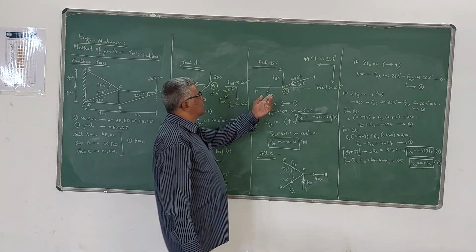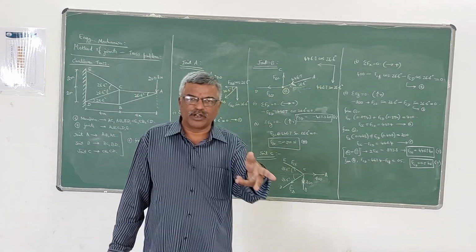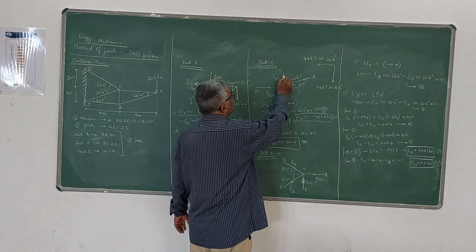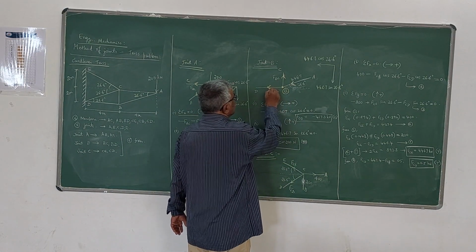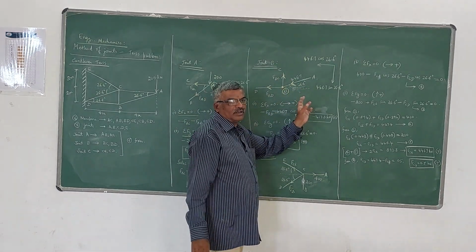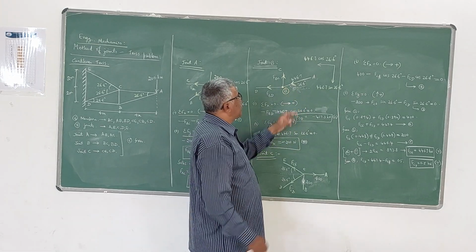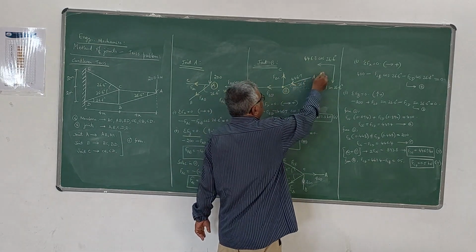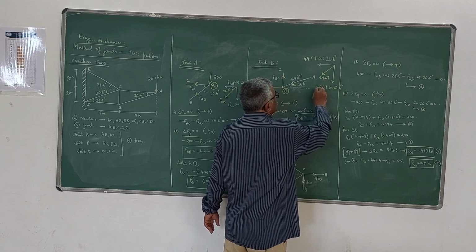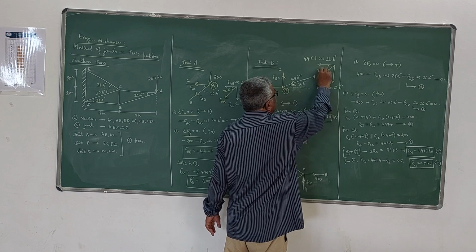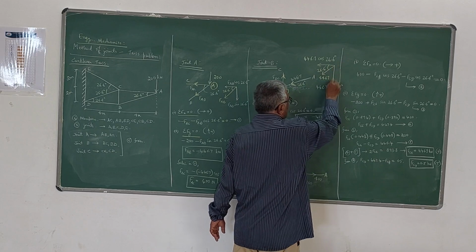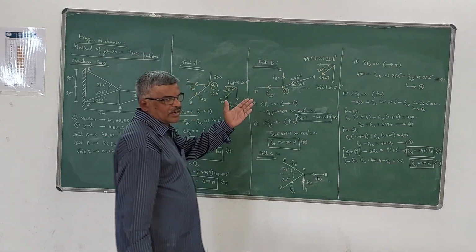Now we don't know the forces in BC and BD. Those two forces we have to find out. Initially we will assume that they are tensile forces. Tensile forces means we have to assume away from B, like this and like this. So this is FBD, this is FBC. Now you have to apply the equilibrium equation for this free body diagram of joint B. Before that, resolve this force of 446.7, and this angle we know is 26.6 degrees. If you resolve that, horizontal component will be this, vertical component will be this, so cos and sin respectively.